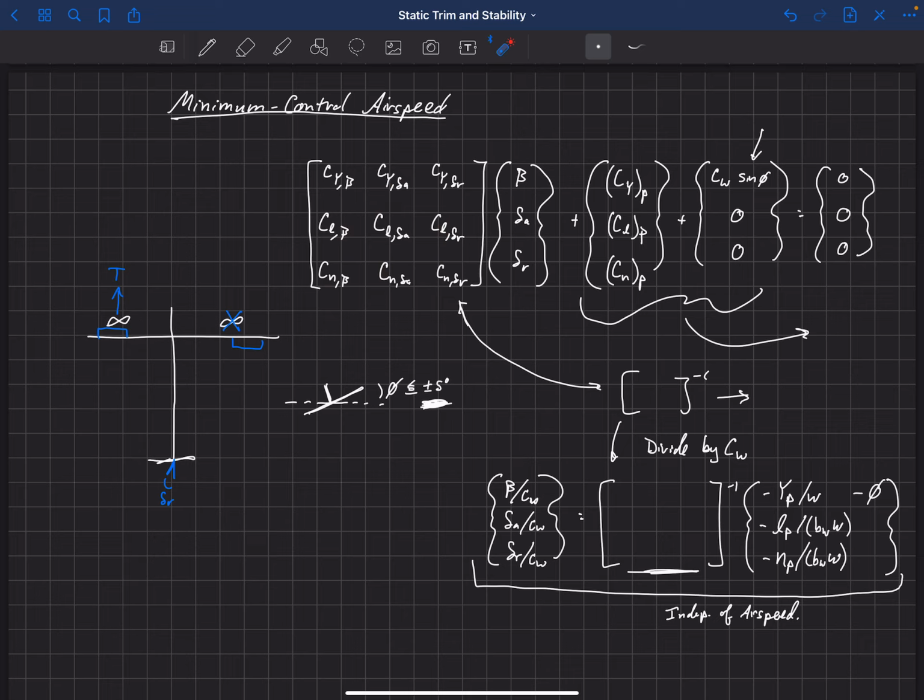And they can change a little bit with Reynolds numbers as we get to higher speeds. They would change with Mach numbers. So once we get up past 0.3, then these coefficients can change significantly. Okay, as we go from 0.3 up to Mach 1, or certainly above the speed of sound, then these coefficients can change significantly.